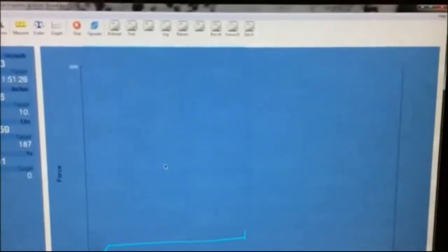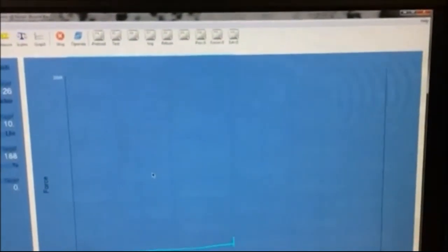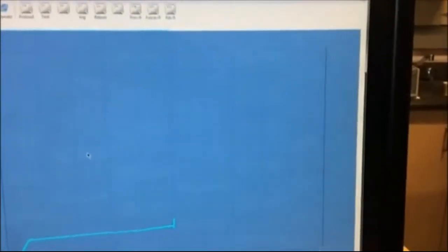This results in a grain structure of fine pearlite with excess ferrite or cementite. The resulting material is brittle. The level of brittleness depends upon the exact and constant conditions of cooling. That's all about the theory part.